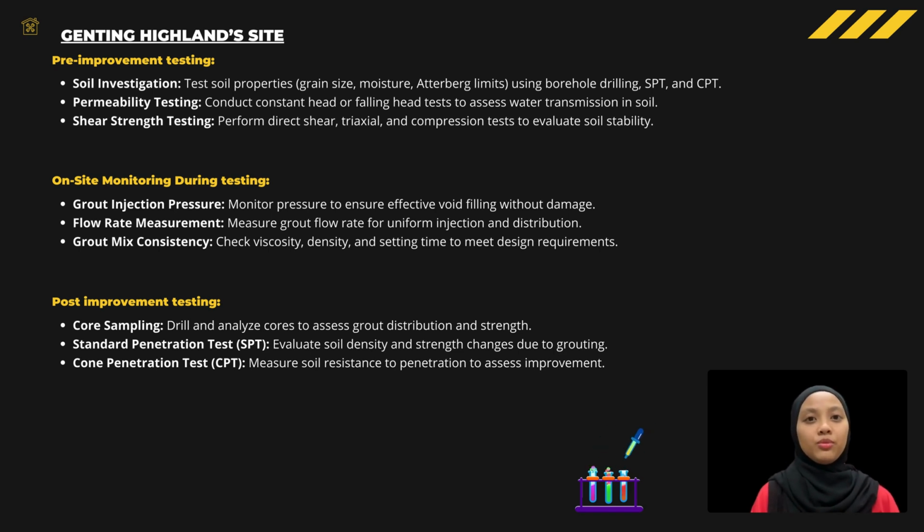Next is post-improvement testing. Core sampling is to drill and analyze cores to assess grout distribution and strength. Standard penetration tests are also conducted to evaluate soil density and strength changes due to grouting. The cone penetration test is to measure soil resistance to penetration to assess improvement.